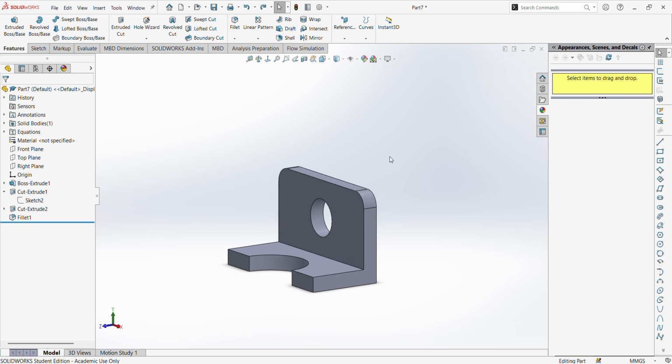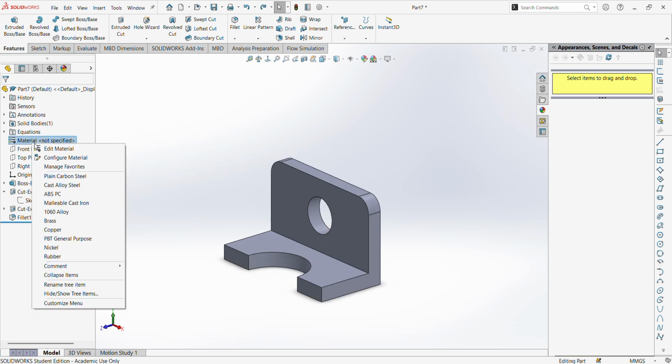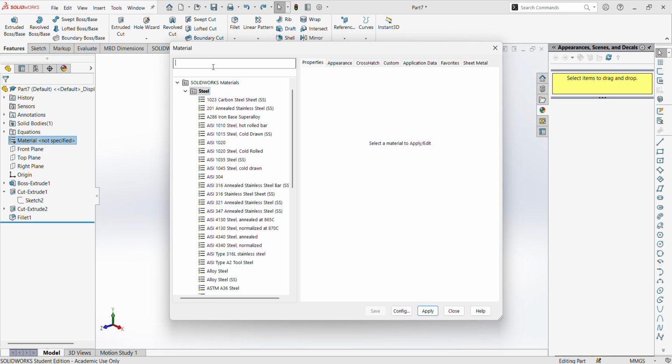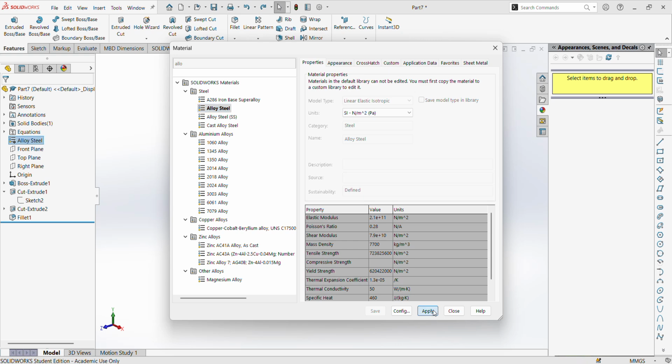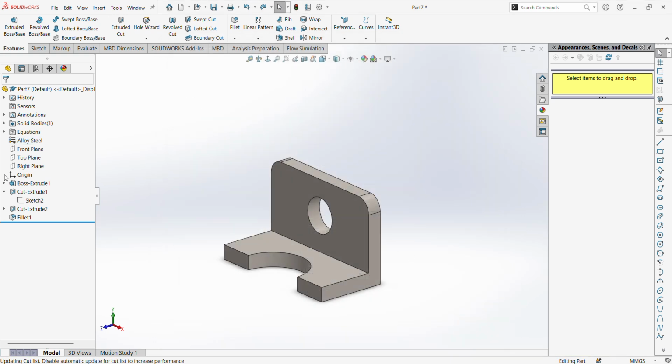So we're going to erase that because it is going to mess with our mass properties. Let's edit the material finally and put in that alloy steel, like I believe was from our materials. I think it just said steel, but we can assume alloy steel if I didn't put anything specific there. So cool, our origin point did work because we mid-planed it from the right side this time. That's awesome. I like the way this worked out. Simple part to build, easy to do, under 5 minutes for this one.